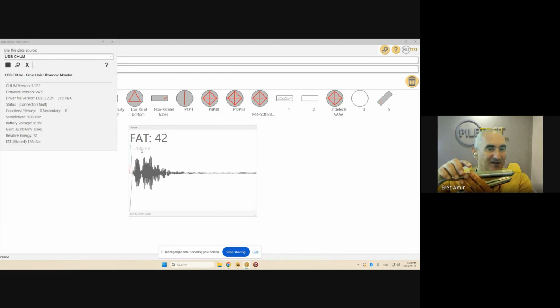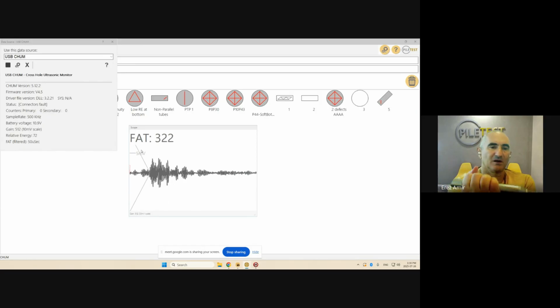Now, another thing that influences that is the material. Right now, the signal goes through air. If I change that and make the signal go through my body, which is mainly water, you can see that the signal becomes much, much stronger. Right now it's touching my hand. When I disconnect, it's immediately 10 millivolts. Touching my hand, 1 volt. Not touching my hand, 100 times weaker.